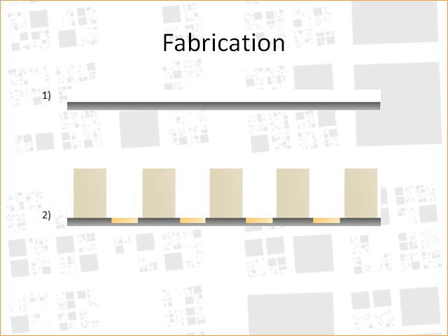Also shown in the light gray is an aluminum oxide porous wafer. This wafer can be created by oxidizing aluminum and then etching away the remaining aluminum. It has holes on the microscale and is an inexpensive way to produce a fairly regular microscale structure.